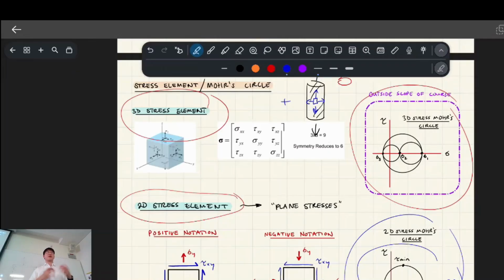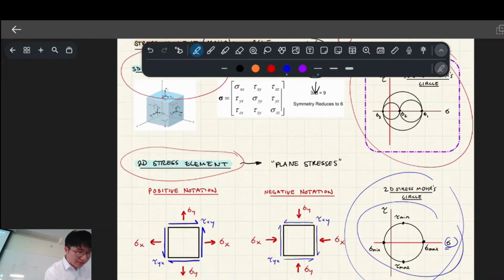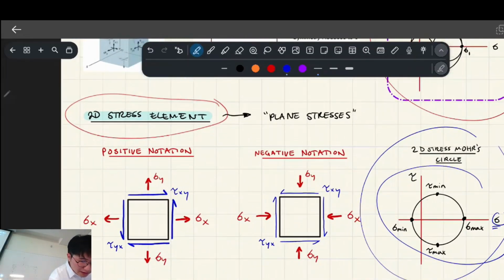Or if it's experiencing, let's say, 1 MPa of compression, it'll be negative 1 MPa. Does that make sense? So all of a sudden, our Mohr circle is going to be plotted so that there could be negative numbers on it as well.